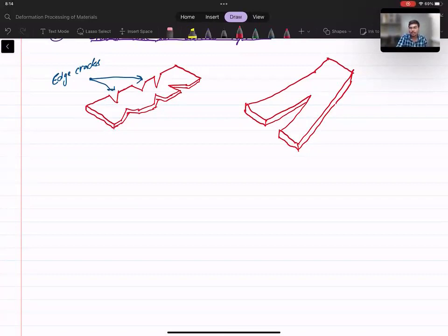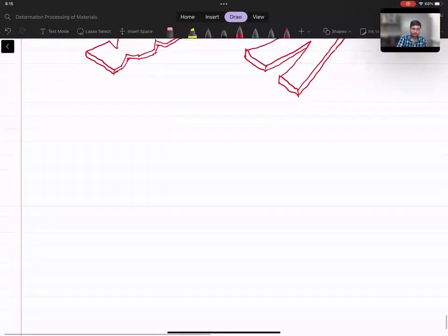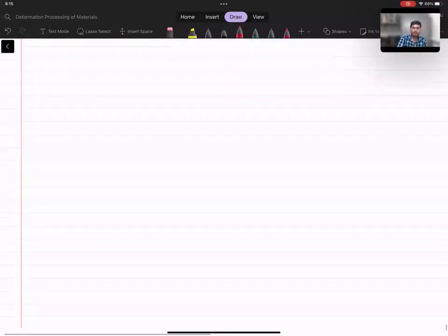They don't get deformed plastically to a great extent. We will consider the elastic deformation only. So that deformation also leads to some defect in the final product, as you can clearly observe: when there is elastic deformation, the desired thickness will not be achieved and a higher thickness of the component will be formed at the end. Okay, so that will be termed as mill stretch.